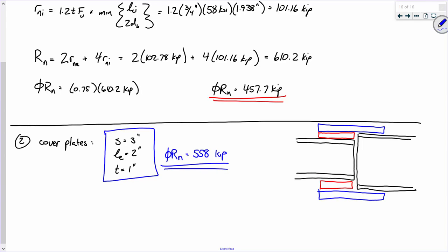So, in other words, if you go through and carry all of those bolt bearing calculations again for those numbers, and I'm not going to repeat it because it is literally the same thing we just did, just different values for plugging and chugging, you'll get a capacity of 558 kips. So those cover plates are just fine. There's nothing wrong with those. In fact, it's probably worth discussing taking those cover plates and making them, instead of 1/2 inch thick, maybe 3/8 or maybe even a little thinner because they're certainly not governing the design. So all in all, that capacity is fine.